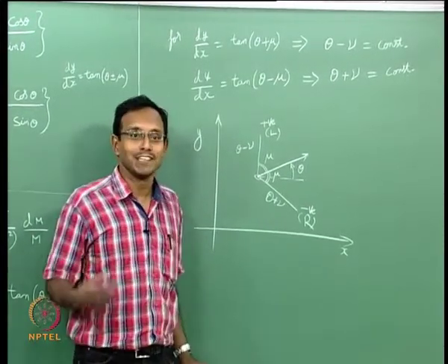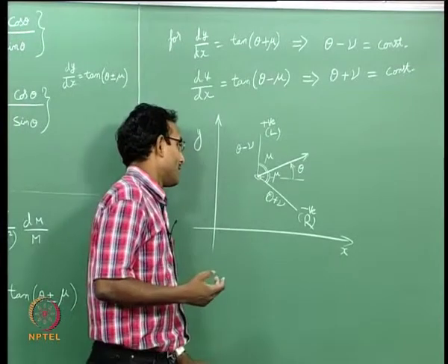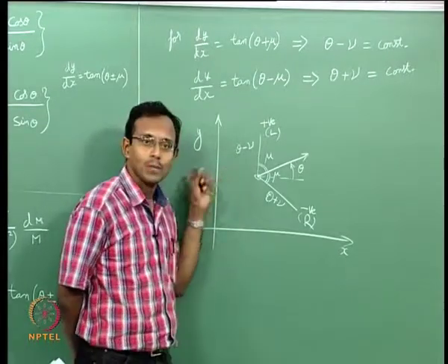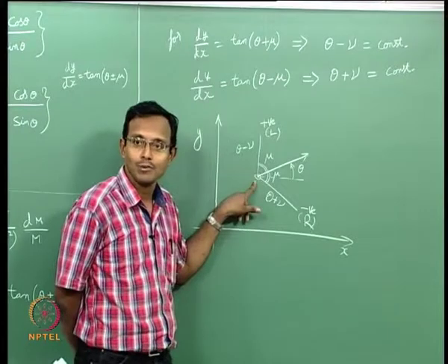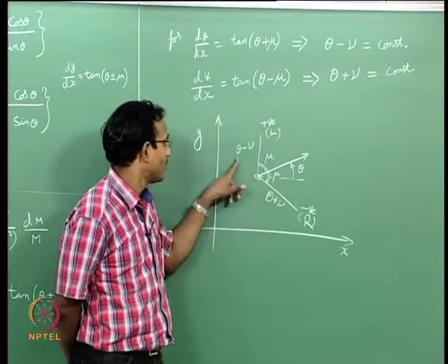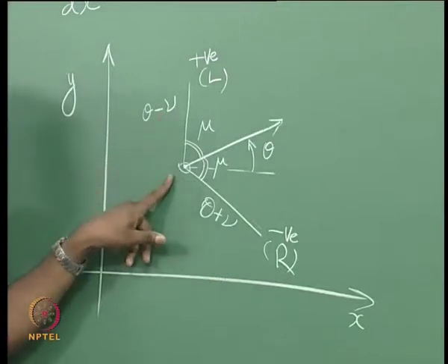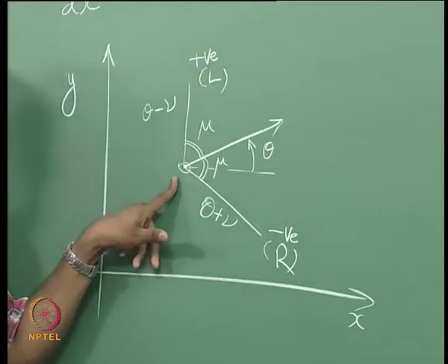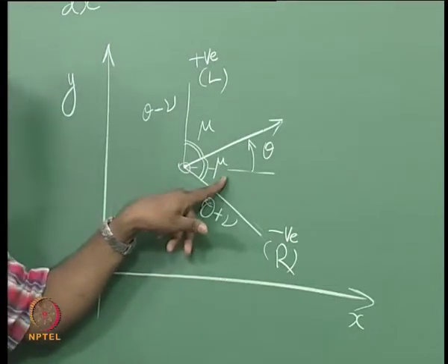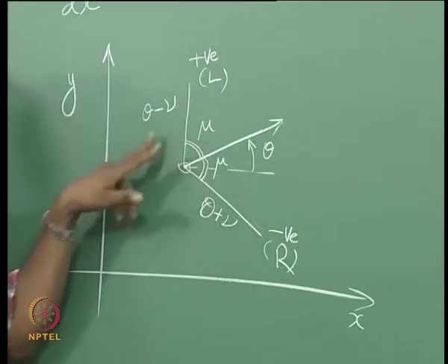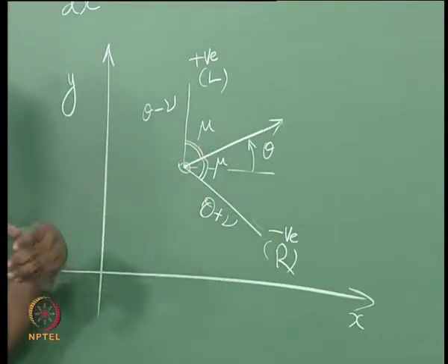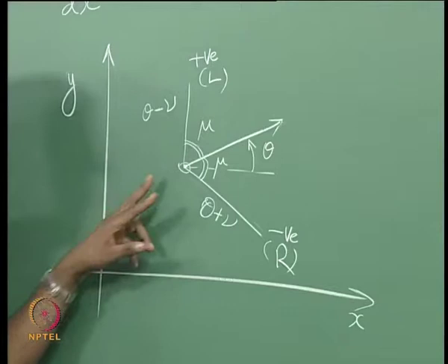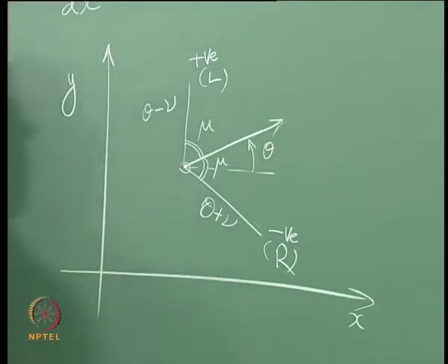Ideally in gas dynamics typically it is 2, okay. But we got this thing, where are those two constants, two numbers that specifically talk about this point? I can think about theta and nu probably at this point. That is one way of looking at it. Typically people use theta and Mach number, because once I get Mach number I can get this mu easily. Of course I have nu, from there I can get Mach number and get mu also. Typically people store theta and Mach number at every point, okay. That is how typically people work with in method of characteristics.